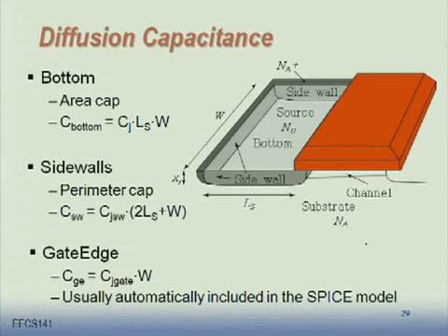Now, when you calculate the sidewall capacitance, books will typically say that it is equal to the two lengths of the diffusion plus one width of the diffusion. What happened to this other width over here that is sitting under the channel? Why are we not counting on that one? Isn't there a fourth side of a polygon? Charged in the channel, but it's a thin layer, right? I mean, this is deeper things down there. So yes, because of that electrical connection, we used to ignore it.